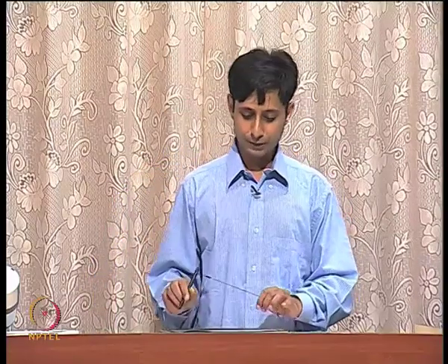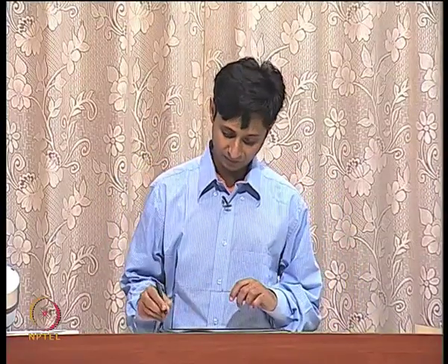Okay. So, what you have reduced over here is V effectively. You have reduced the quantum of V over there, each loop has much lesser V. Okay. R is also proportional to V, but net result is that if V goes down 2x and R also goes down 2x, then what is going to happen to the power lost? Power lost is also going to go down by 2x. So, that is what happens in this case.